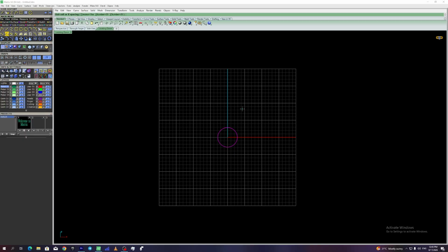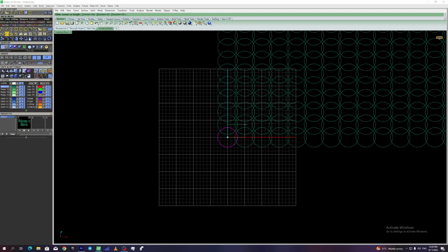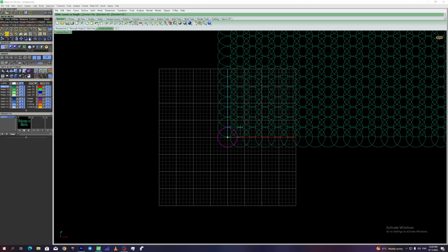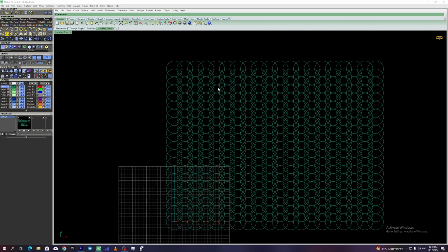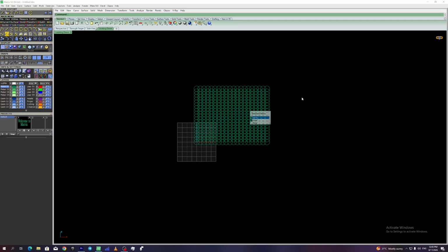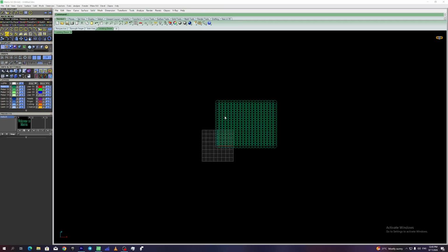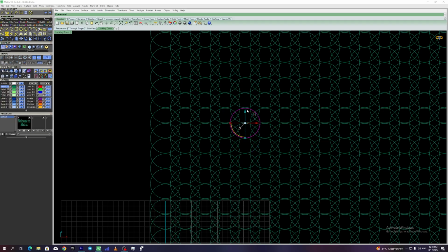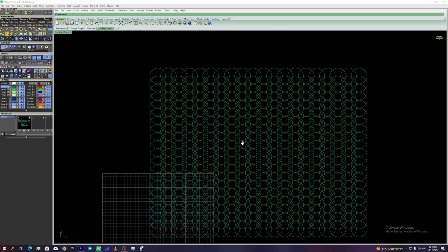Before we start trimming, let me remind you of an important tip I mentioned earlier. Zooming in is crucial, especially when you're working with small objects. Also remember the difference between dragging from left to right and dragging from right to left. This affects how your selection works.